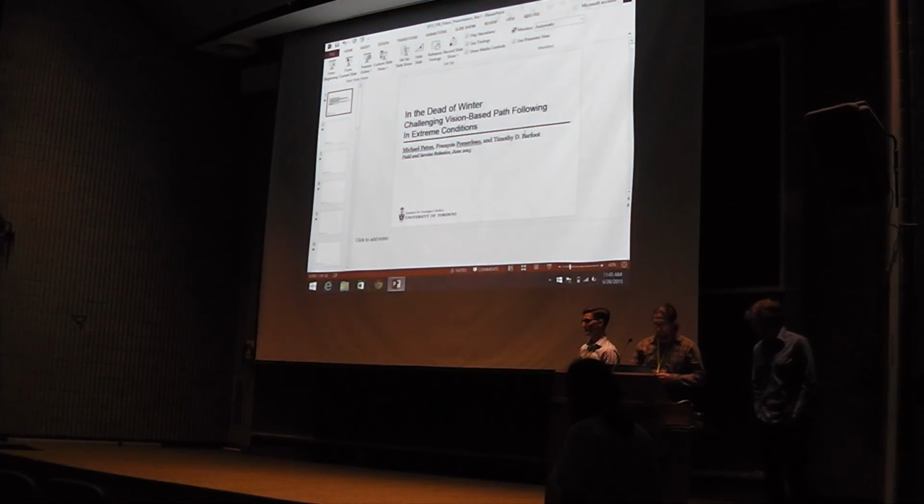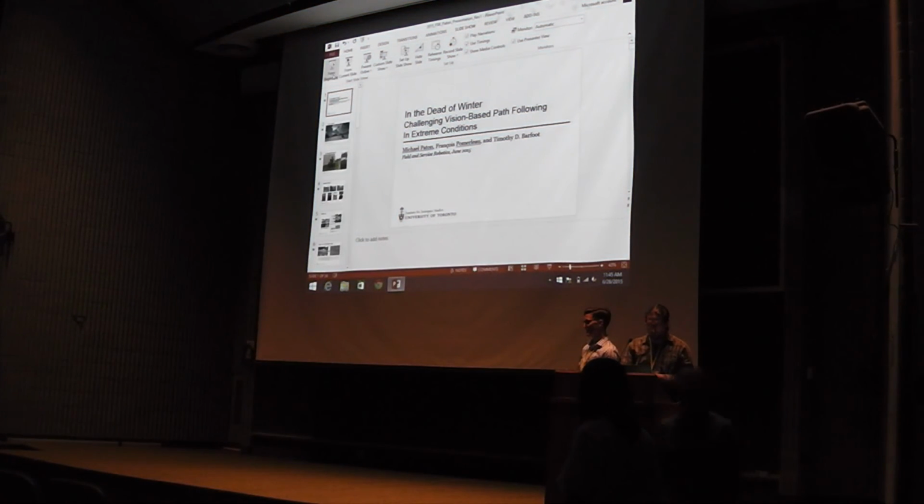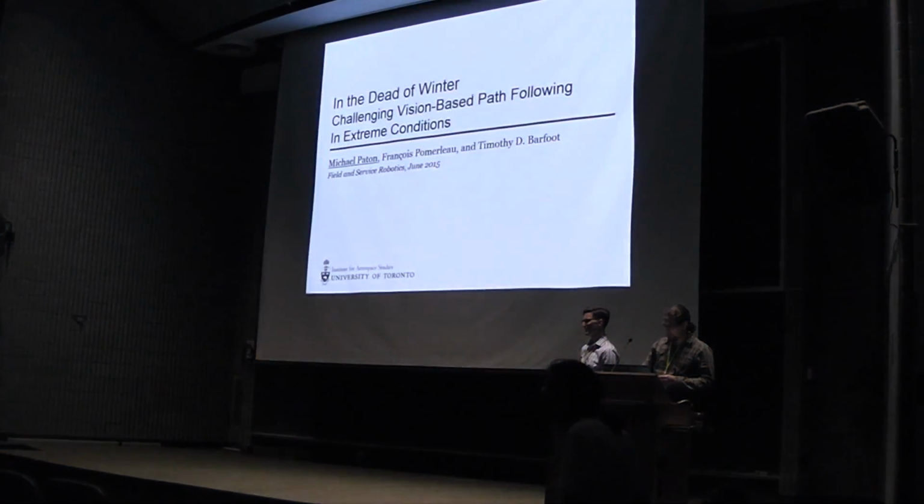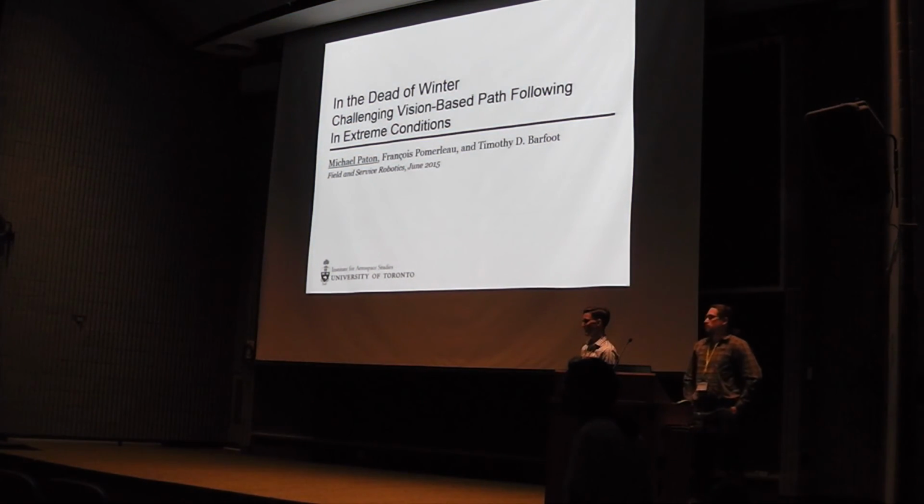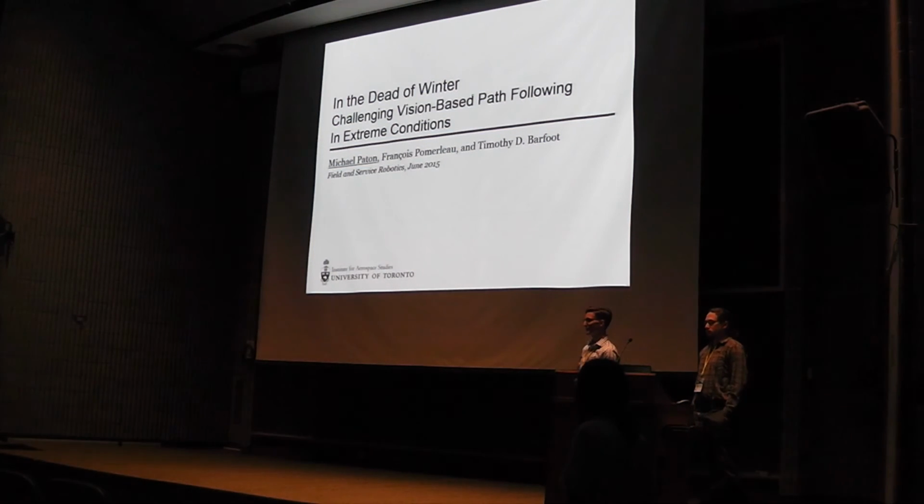Yeah, so our system uses SURF features, and we stuck with that just for consistency with the stereo pipeline. We definitely have thought about doing this with direct methods. We're operating at 15 frames a second just because that's the maximum that our camera can put out in this configuration, and it's not entirely clear to me if that would work that well for direct methods, but we've definitely thought about trying it. It has definitely worked for us at 1 meter per second average velocity at 15 frames per second.